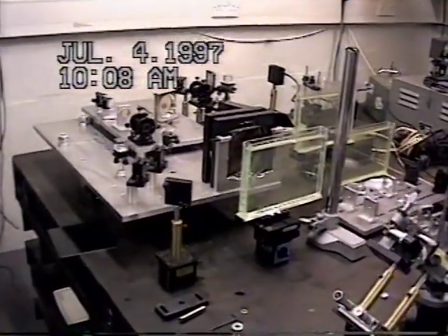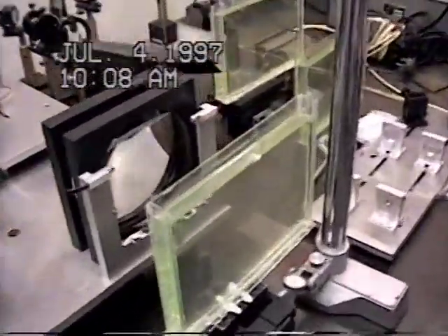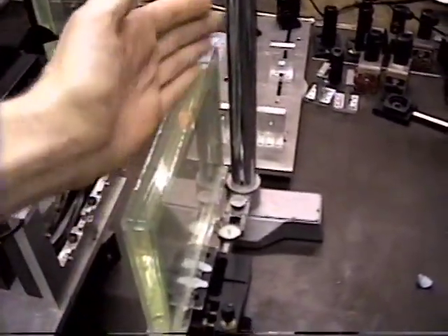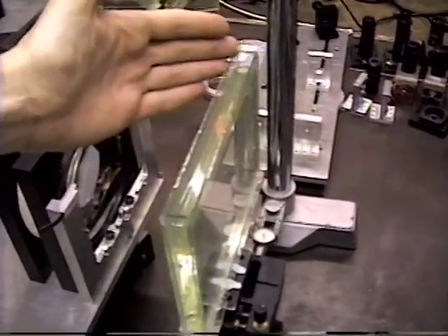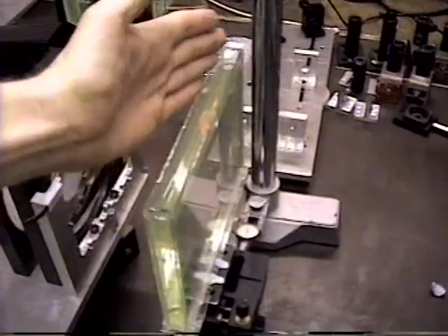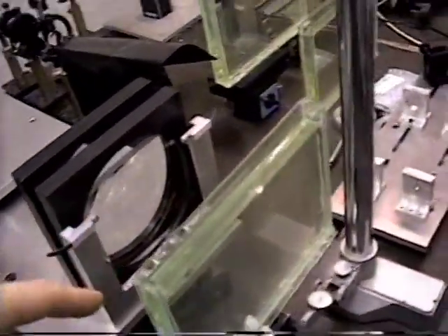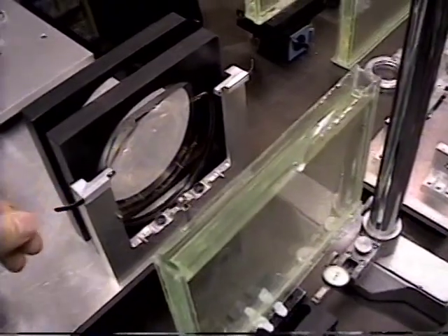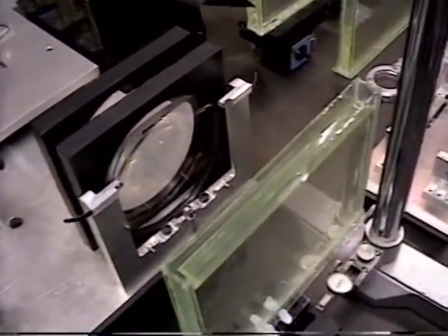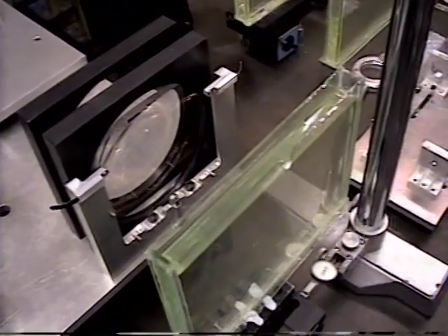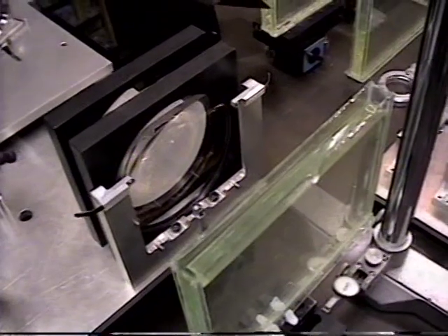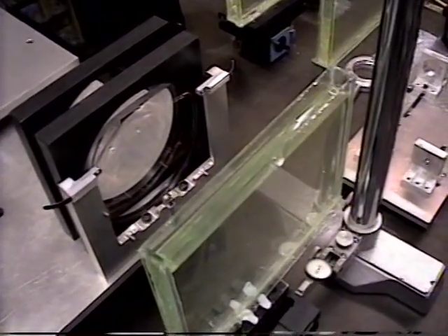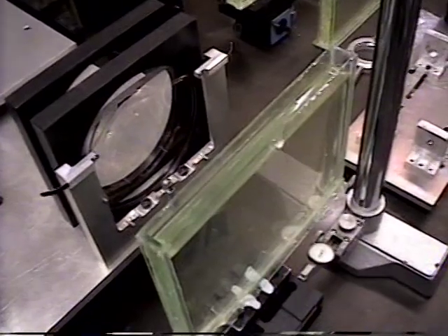Okay, yesterday I made a hologram of this tank, which was rotated so that the particles shifted in the Z direction, the out of plane direction. Before doing this, I made a computer model of the fringes and what the fringe patterns would look like, and from that I determined what the maximum displacement I could hope for to get viable fringes into the optical processor.